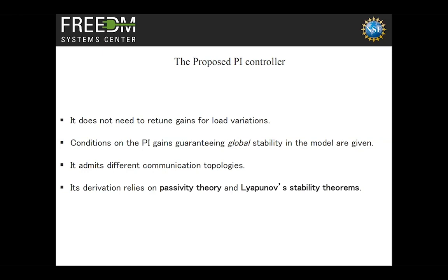Now, how is that possible? How can you have a nonlinear plant and still have a linear controller? This concept has been very popular in control theory, where we do appropriate projections on the nonlinear system and bring it down to a simple looking plane where I can still design a linear controller, and the linear controller can stabilize the nonlinear plant. The upshot is that if you do those kinds of transformations, then you lose controllability. So the simplification of control design comes at the price of controllability. And here, the message is that if you can make use of system-specific properties, actual physical properties such as passivity, then you can still guarantee closed-loop stability despite having that loss of controllability.